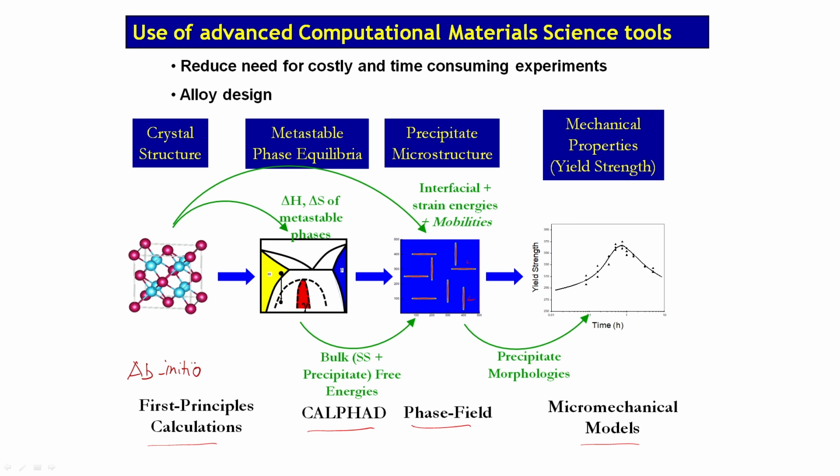So, this is what was taught by the guest lecturer Professor Tarun Kumar Kundu in the last 2 lectures, lectures number 32 and 33. Then from this information we can calculate a lot of thermodynamical parameters like enthalpy of mixing and entropy of mixing, or we can determine them experimentally also, extrapolate also, as I have shown you in my lecture, and find out phase equilibria and phase diagram information. It can allow us to find information of phase equilibria of the equilibrium phases as well as non-equilibrium or metastable phases. So, that provides us the phases present, but it does not provide you microstructure.